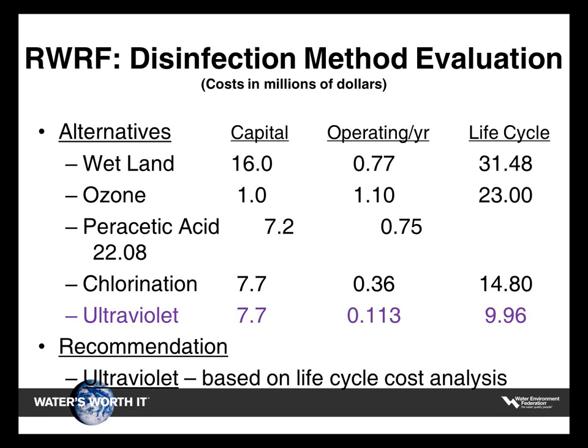We did not want to go chemical. I was very much opposed to any kind of chemical disinfection for reporting reasons, for dose reasons, and regulatory reasons, because something that may be okay today, we were worried wouldn't be okay 5 or 10 years from now as far as the chemical dosage. So we chose ultraviolet light.